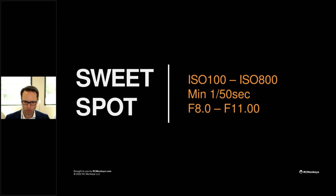We're experimenting with f-stop, and we're trying a lower f-stop, and it works well if you're shooting ortho photos, so everything that's in the same plane will be in focus. But once you shoot at an angle relative to your subject, you'll have a portion of the image that's in focus and other parts that will be blurry. So between 8 and 11, that's usually the sweet spot. If you go higher, you might get some artifacts. You can search that. You'll find a lot of information about what happens when you shoot at a much higher aperture.